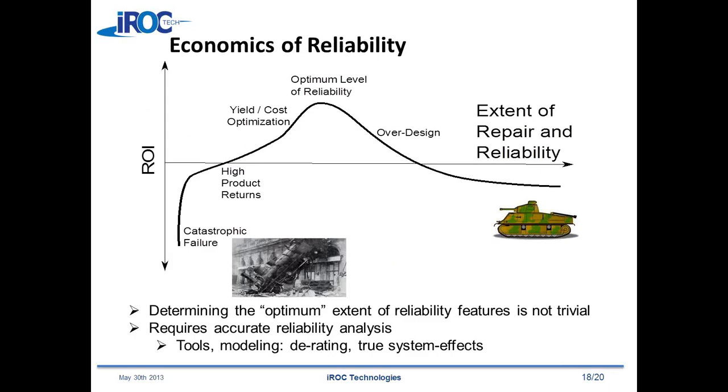There's clearly a cost associated with performing accurate SER or any other reliability analysis on a chip, and there are very real costs associated with mitigation, whether that's ECC or hardened flip-flops. Those costs come in area and especially in additional engineering costs. And so it is tempting to try and cut corners.